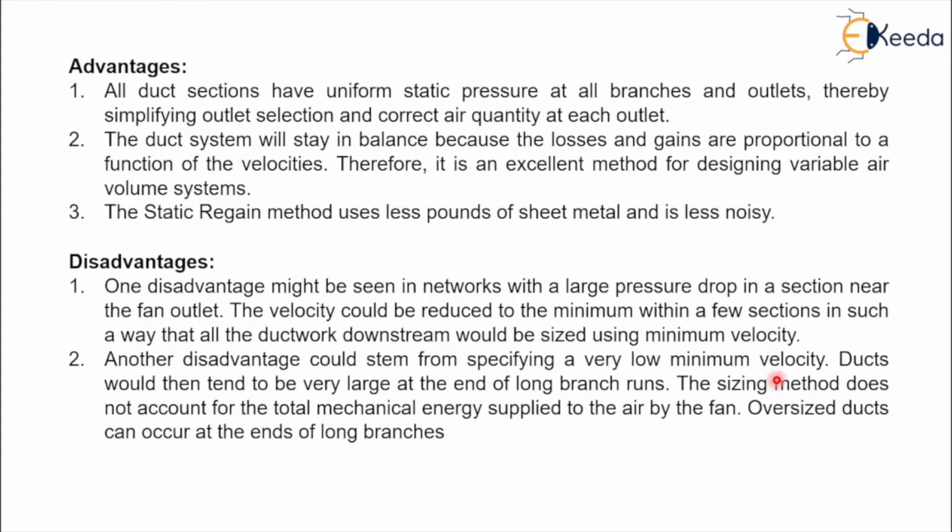So if velocity is less at the end of a duct, then the size at that point will be very high, because you know Q is equal to area into velocity. If velocity is very less, then area will increase, so the diameter of the duct will increase. That's why the size of the duct will increase.